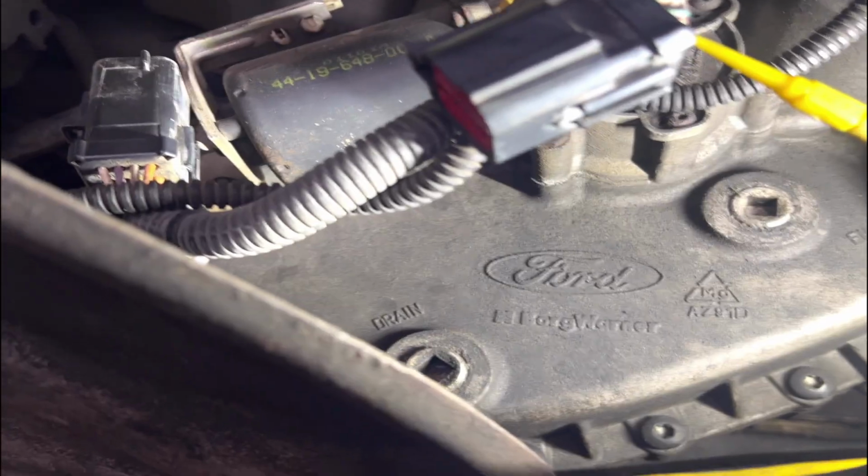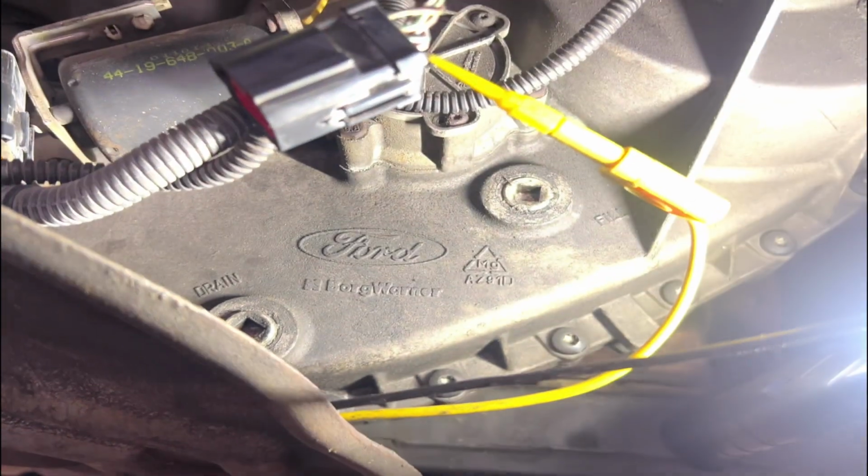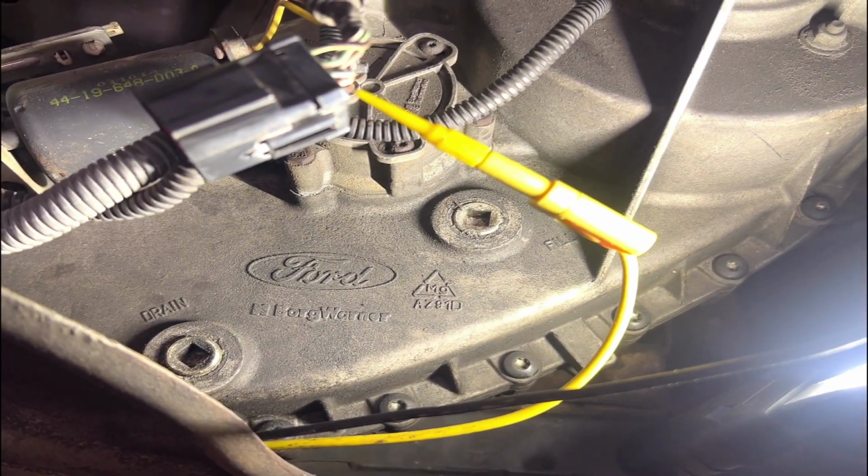I really think we need to go to the transfer case control module and make sure this voltage is the same as output from the transfer case control module. So we are in a moment where service information might be wrong and is less than helpful. I've been doing a bunch of trouble-tree reading, description operation, make sure I'm not missing something, but I will get you caught up to where I'm at, and then I think we're going to make a call. I gotta walk you through this.